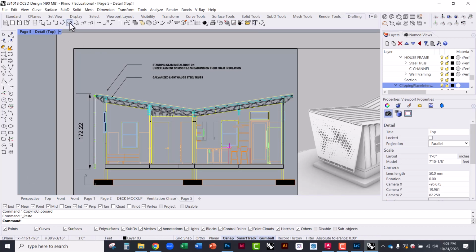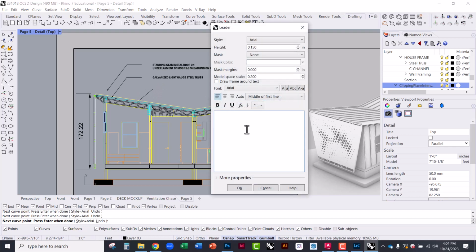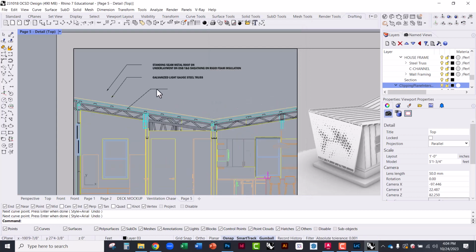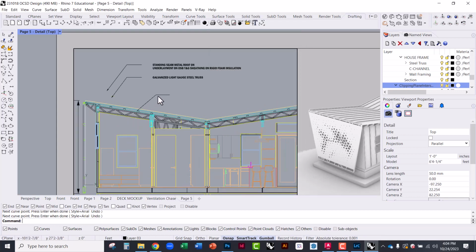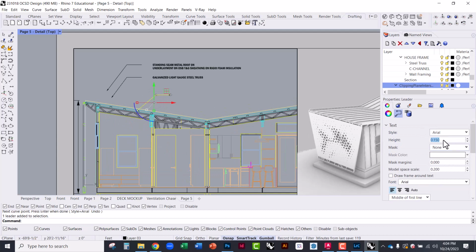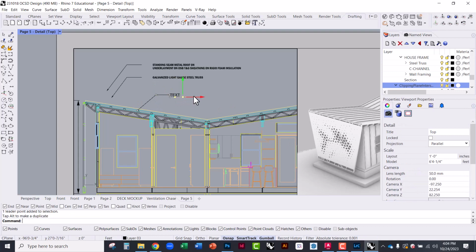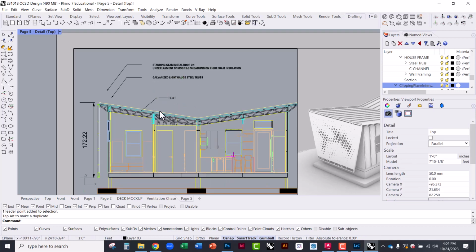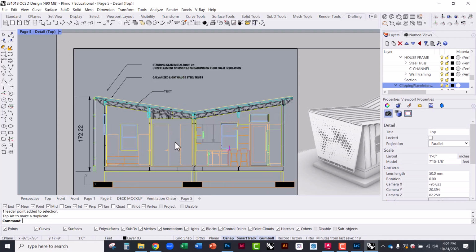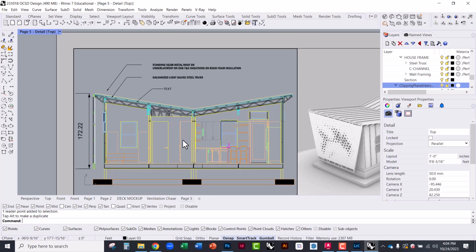Actually, I'll have to redraw it, but it's the same idea here. Hit Enter, text, and now when I zoom in, I can change the scale of that drawing, and it changes the scale of that leader as well. So you can set that to 2. You can scale with the grips here. So that is scaling with my zoom because I did it in the model space.